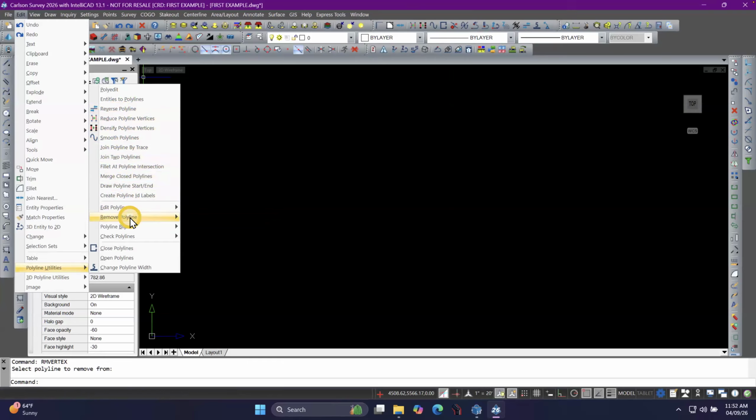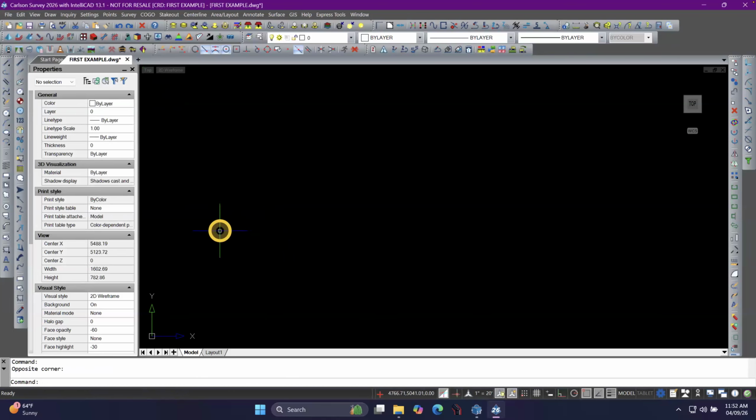What the icon means is that those commands, and these are the 2 that I use quite often. There's also remove polyline arcs, but there's no icon. Remove duplicate polylines, again, no icon. What the icon means is that that command exists on a toolbar somewhere. It doesn't tell you which toolbar it's on, but it just tells you.